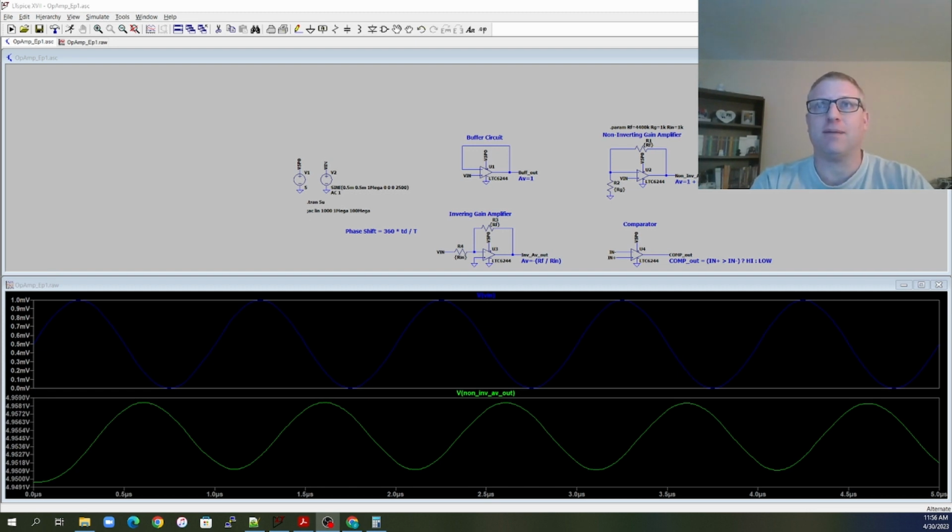But the same thing that we saw happen with the VCM, where we exceeded the VCM on the input and it didn't give us our output, the same thing could happen if the output is not rail-to-rail. If you tried to output something that was greater than that, then we would not see it, right? So just keep those things in mind.